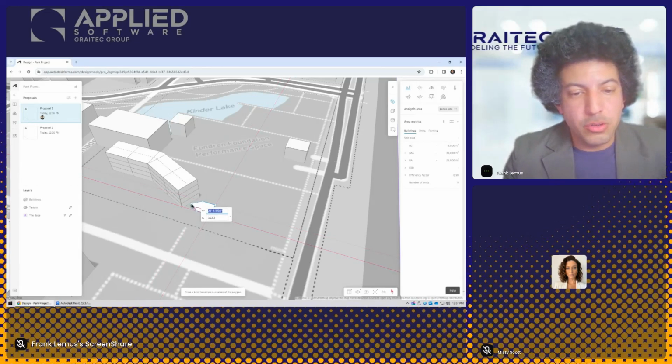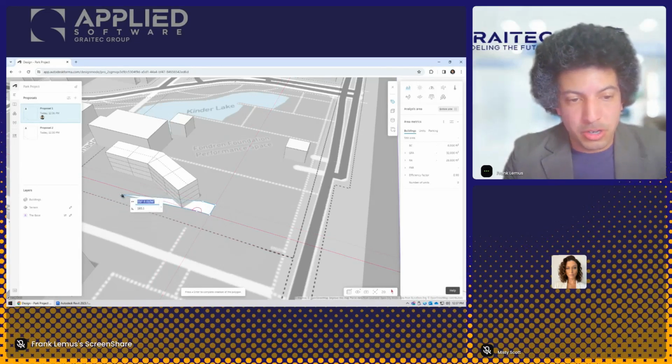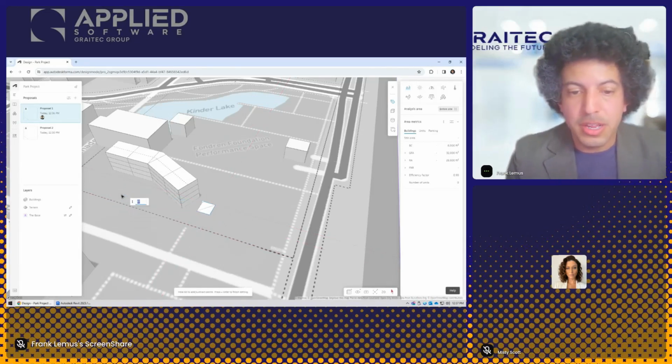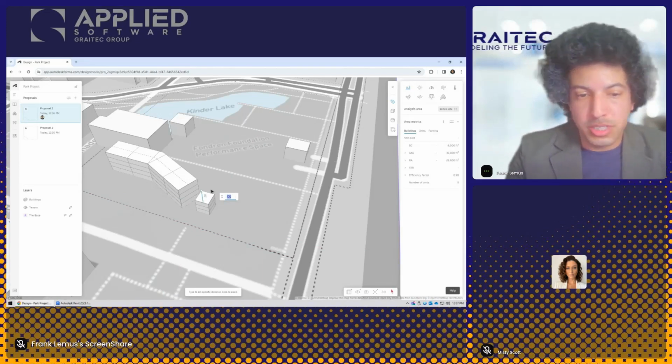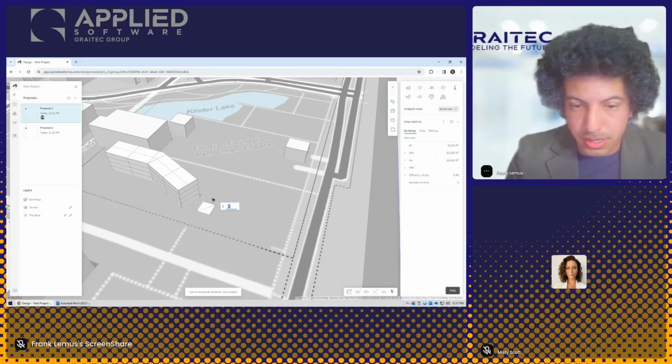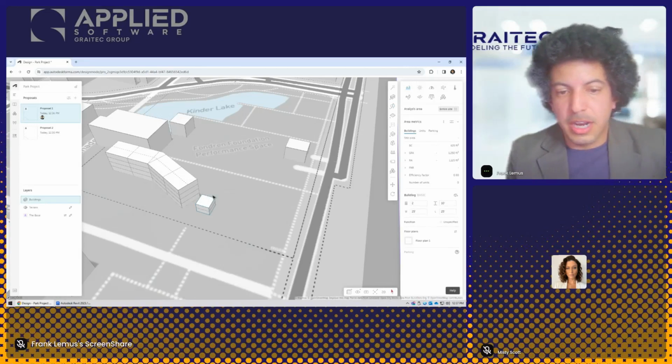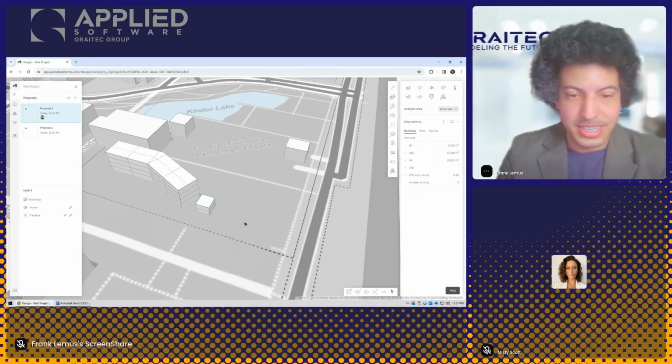Now, it's automatically going to close this, so look how I move my cursor way out there. I'm just going to press Enter, and it's done. Now it's giving me what height I want. Let's just go with 20. And I'll press Enter. Again, it's Enter, not Escape.